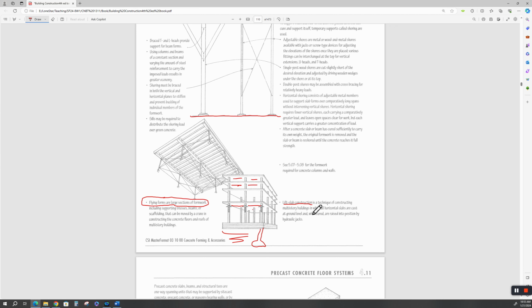All right. Now in silos, concrete silos or water towers, they'll use a very similar system, but it's called slip forming. You got this lower section poured, and then when that cures, they got the rebar going up. Then they'll jack these forms up, tie them in around the circle. This is a tube, okay? And then they'll pour the next section. And when that cures, they'll jack these forms up, and it's called slip forming.